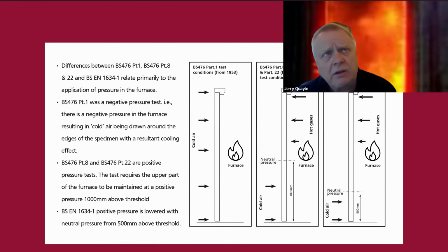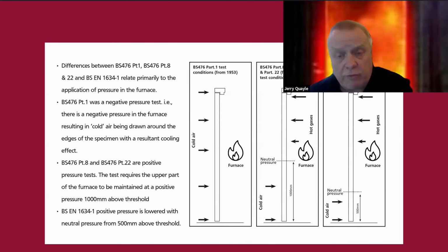Indeed, they decided that there was a case to answer to use a different thermal recording mechanism. So the thermocouples were changed to these plate thermocouples. They work very well for non-combustible materials, but for combustible materials, they have a negative effect. And indeed, some of you will be aware of the fact that there is almost a reduction or a slowness for these plate thermocouples to actually reach the recorded temperature from within the furnace.